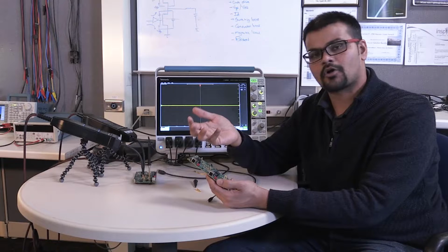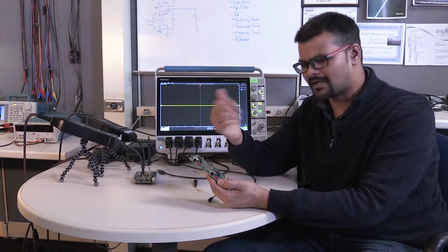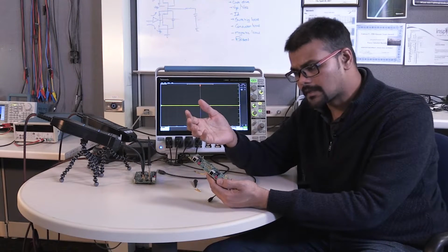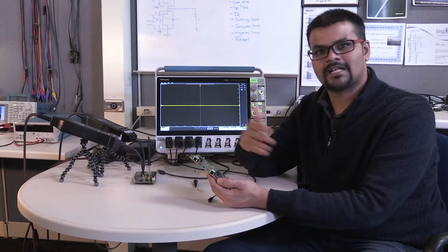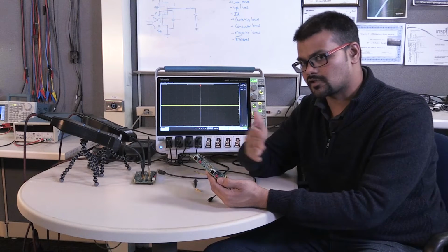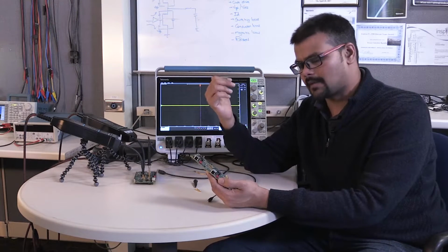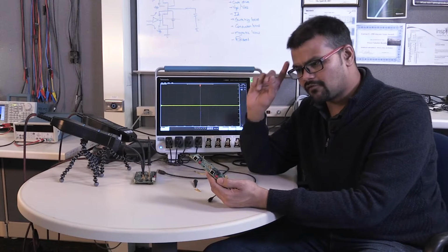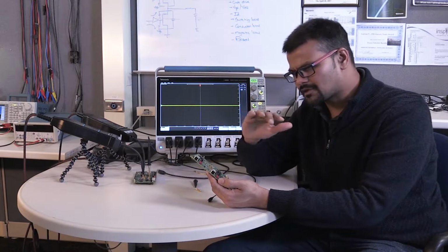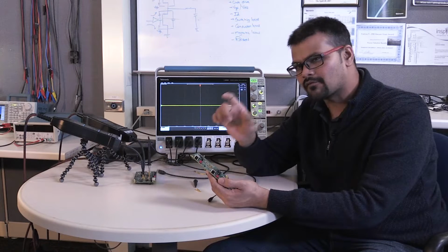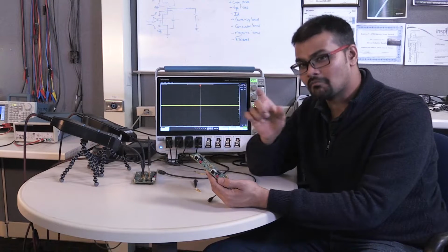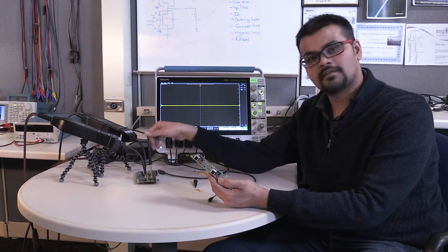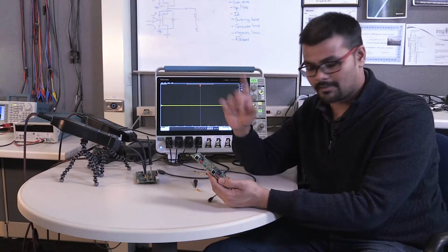Most of the GaN products in the market right now, from GaN Systems, EPC, Transform, the turn-on times are usually in the 10 nanoseconds, or 5 or 6 nanoseconds range, and we'll see a very similar example here. And if you think about how much bandwidth you actually need to measure that transition, with a very simple rule of thumb, that is the number you come up with. So bandwidth is one piece of it.